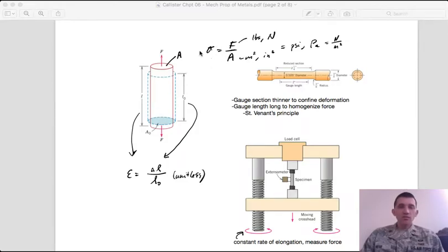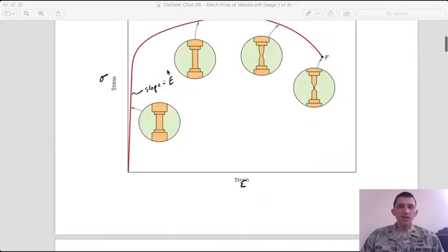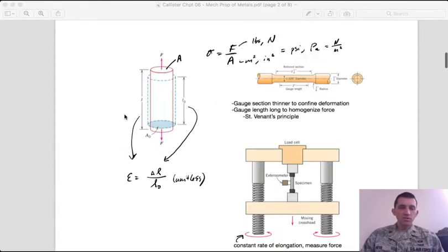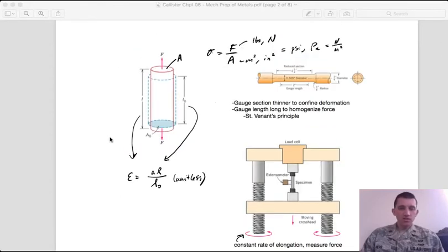So we're not applying a force, we're applying a stress. That would be units not of newtons, but of newtons per area, newtons per square meter, or Pascal. So that would be a unit of pressure. The English equivalent would be pounds per square inch. So we're applying some force over an area, and that gives us sigma, or the stress component of our stress strain curve.